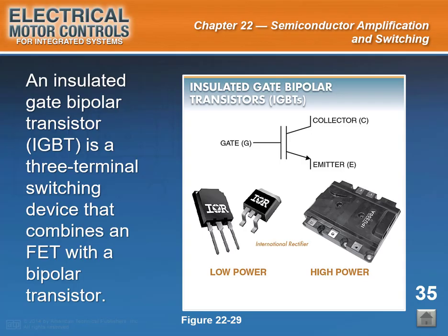But high-power MOSFETs are voltage-controlled devices and do not require much, if any, current to control them. So, it makes sense to build a transistor that combines the benefits of both transistor technologies. By putting a high-power MOSFET on the input to the power BJT, the input to the MOSFET will not demand high current, because the voltage-controlled MOSFET will deliver that current based on the voltage on its high-impedance input, and the power BJT will then deliver the high current output that is required to the low-impedance load. This IGBT solves the weaknesses of the power BJT by introducing the power MOSFET on its input.